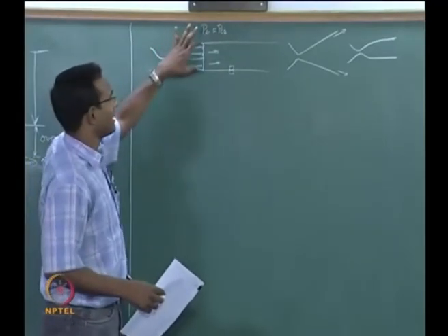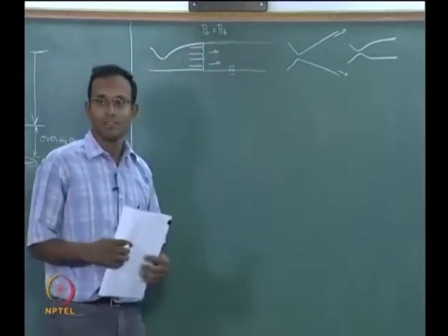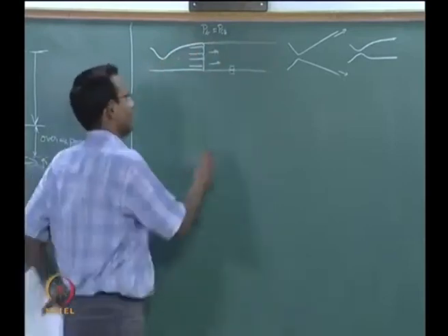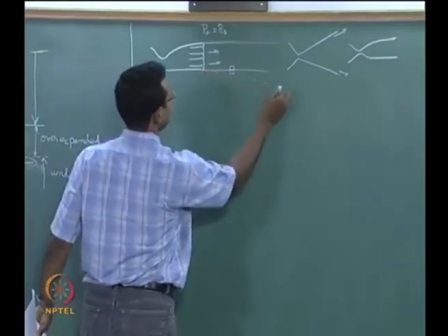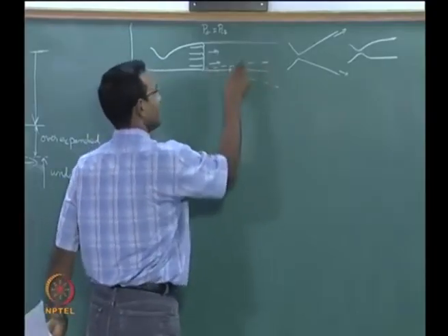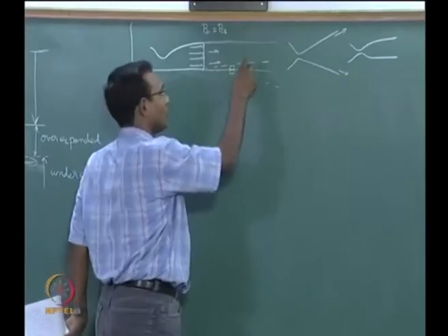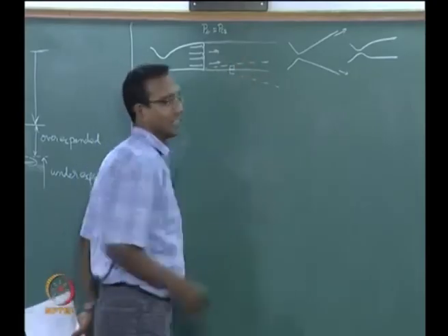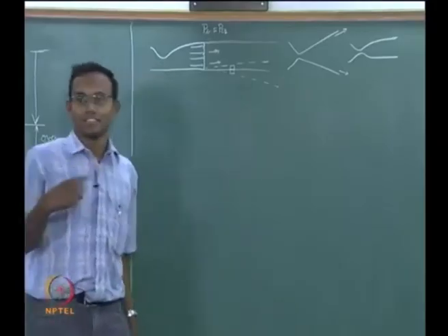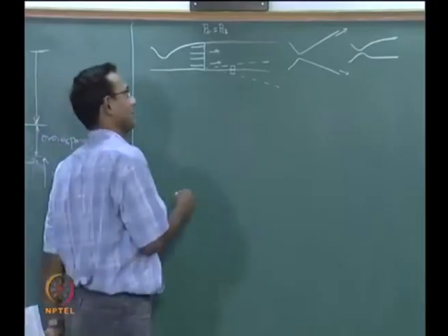That region wherever there is higher mass flow will just keep moving like that. In reality, there will be some viscous shear stresses developed in this region, and so this region will become slower, this region will move faster. And so you are going to develop this whole dotted line region, called the shear layer, the region where shear forces are important.